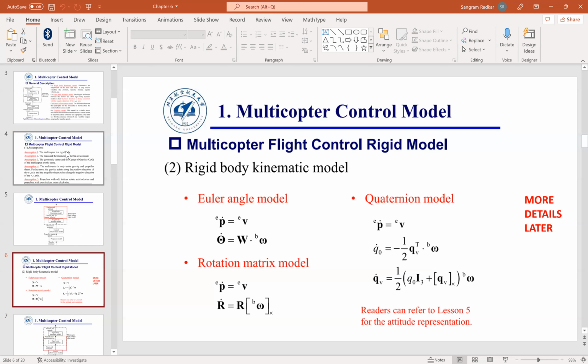Also, please understand, you cannot add dollars to pesos, dollars to dollars, pesos to pesos. In other words, if you have the velocities on the left hand side, they are expressed in the Earth-centered, Earth-fixed coordinate frame. You cannot equate that to the aircraft body coordinate frame. Everyone understood? Dollars to dollars, pesos to pesos. You cannot equate velocities in the Earth-centered, Earth-fixed frame to the velocities in the aircraft body frame. You would need to use a transformation matrix that will make that whole thing consistent. So this simple innocent looking equation is actually three equations that consist of transformation matrices, and we'll derive those step by step.